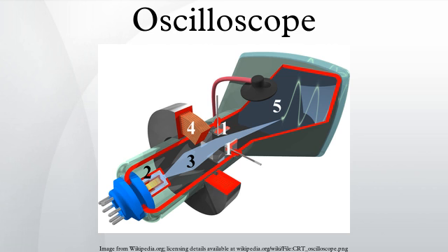Some digital oscilloscopes can sweep at speeds as slow as once per hour, emulating a strip chart recorder. That is, the signal scrolls across the screen from right to left. Most oscilloscopes with this facility switch from a sweep to a strip chart mode at about 1 sweep per 10 seconds. This is because otherwise, the scope looks broken; it's collecting data, but the dot cannot be seen.